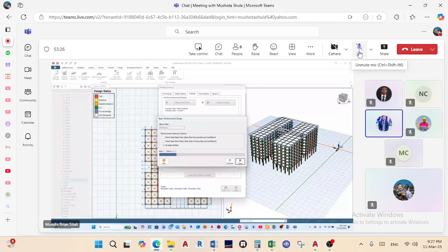So remember when you were doing column design in university, if you're doing member design, either a column or a beam, the first thing you have to do is design for the cross section first of all. There were those checks like slenderness, deflection. Before you even think about calculating the area of reinforcement, you first have the cross section satisfactory.